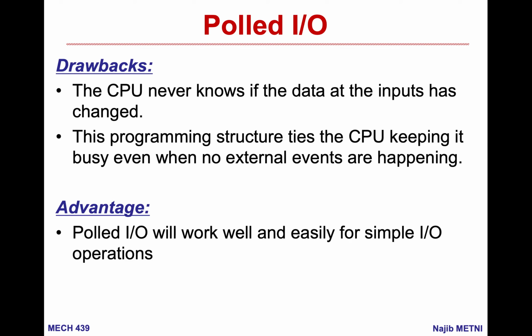In terms of the pin working as output, I do not have any problem, because whenever I want the output to be high, I will write a high on this pin, and if I want the output to be low, I will write a low, and the output will be low. The basic problem is when I have the pin behaving as an input.